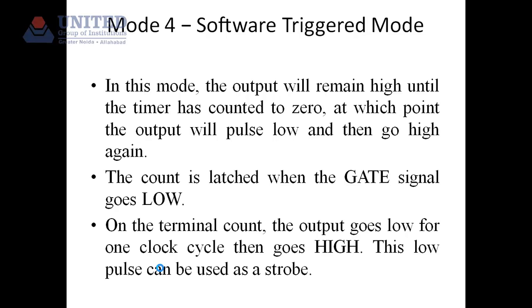Coming on to mode 4, that is the software triggered mode. This is a very famous mode. Any triggering which is done during the program, the software which we have written, is known as mode 4 or the software triggered mode. In this mode, the output will remain high until the timer has counted to 0, at which time the output will pulse low and go high again. I repeat, it will go high again.